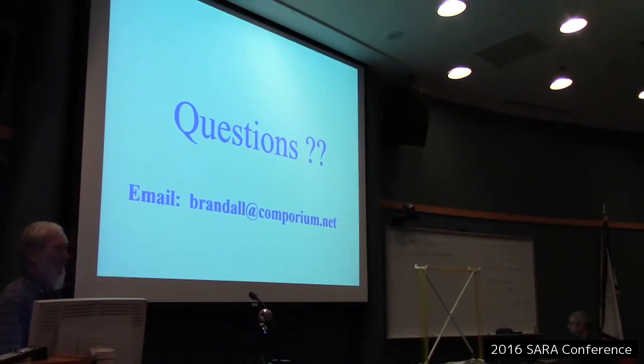They do need to be held so that both sides, those polished surfaces, are pushed together rather firmly. What I was talking about is they don't work over massive frequencies. Oh, well, yeah, all ferrites, by the way, have a frequency range. Look it up in the catalog. For a particular ferrite, you see ferrites that work good at low frequencies, and at 50 megahertz they just lose the ability to choke off signals. They're hardly there. You'll see another grade of ferrite that begins to work a little bit at 30 megahertz coming up, and it'll work to about 300 maybe.